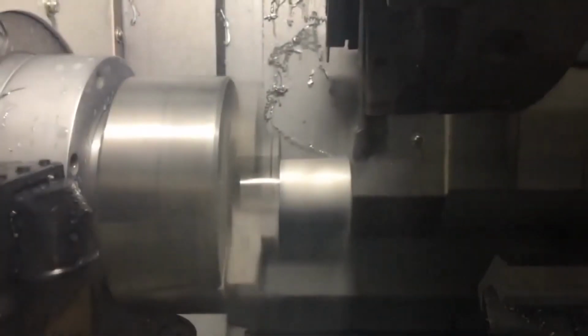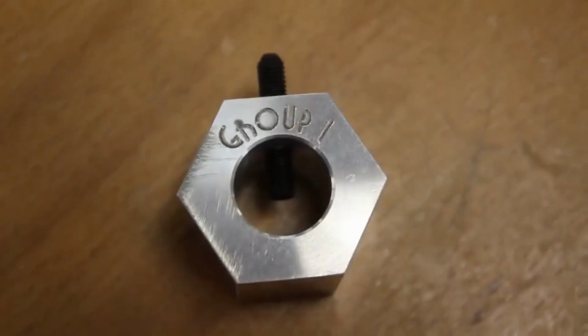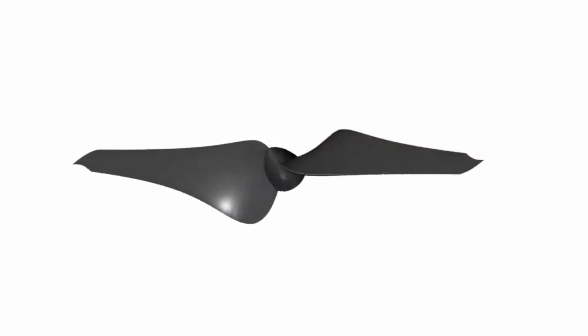Our first step in manufacturing the turbine was to create the hub. This was done via a combination of CNC turning, laser engraving, as well as 4-axis machining. After completing the Creo drawings in CAD files, the blades of the turbine were 3D printed using ABS plastic and a soluble support material. The challenge of 3D printing a hollow section was overcome by leaving several holes in the surface of the blade, allowing for the support material to be removed in an ultrasonic bath at a later stage.